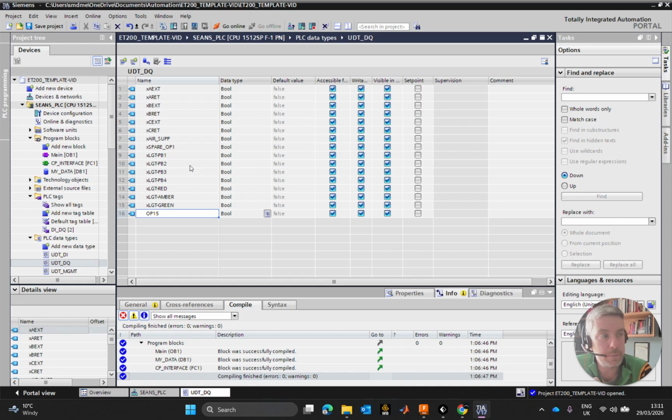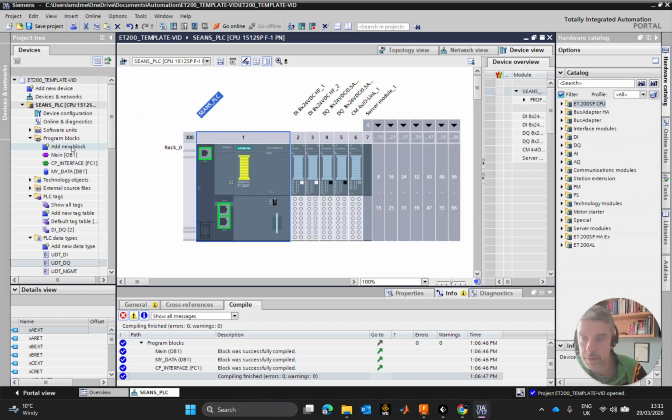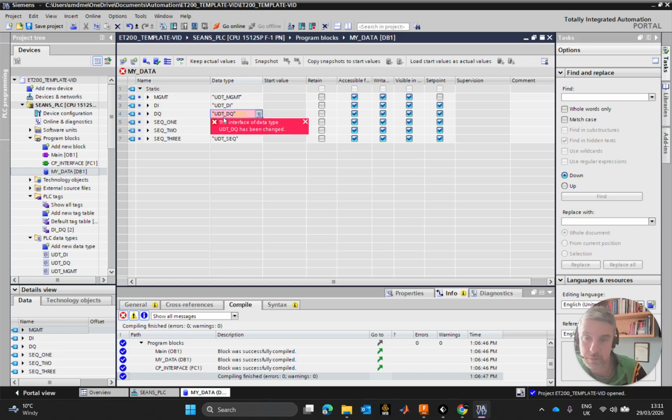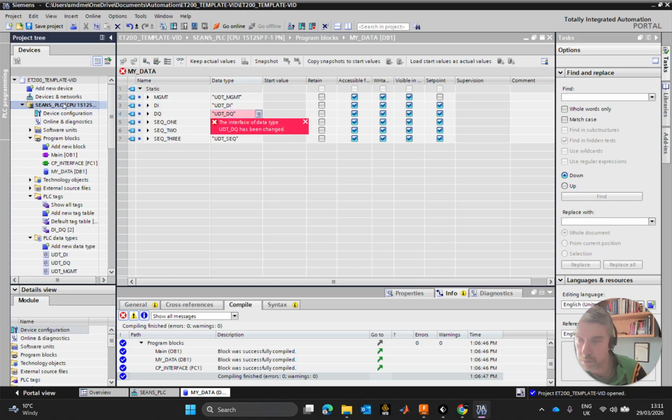Well, we could maybe output to a signal, maybe out to another PLC. But for now, we have a second spare, spare OP2. Done. So again, we've changed the UDT, and what that's going to look like here is a red field for the EQ. I'm going to click onto my PLC folder, click compile, and that gets that sorted out.